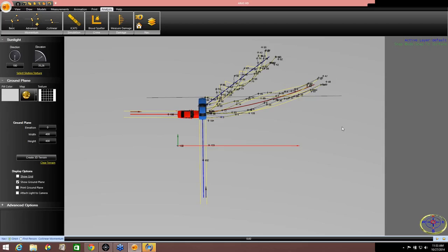Do I have a recommendation on reading tire marks for percent of braking? No, I don't have a recommendation for that. It's just experience out there. You're looking at the marks. First of all, if the marks are thick and black in the road, there's no striations, you've got a pretty good indication that there's 100% braking on that wheel.